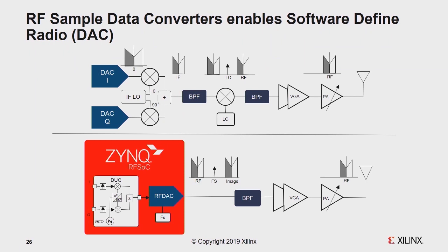So we have a lot of analog discrete components in the system. Now, you can see the bottom line, our RF DAC. We have integrated two IQ NCOs, and then the decimation and interpolation processing. So you don't need to duplicate the whole analog signal chain to implement IQ. You only need one DAC to implement all the IQ signals inside our chip for each channel. And our chip has 8x8 and 16x16 channels. And then at the front end, we can come up in frequency and then VGA and PA going up.